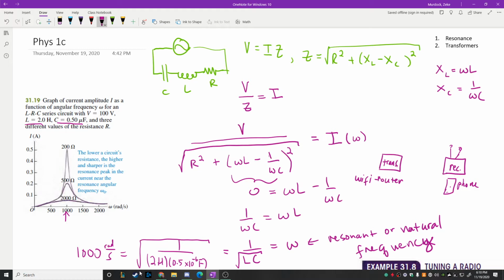But on a radio in your car, if you tune that radio, you tune into a specific frequency. And the idea is that the transmitting frequency, so there's a frequency that comes out from the transmitter, just needs to be synced up to the receiver here. So basically within the receiver, there are either adjustable inductors or adjustable capacitors that allow you to change this frequency. And as long as this right here has the same natural frequency, or the same omega, this is sometimes called omega naught.